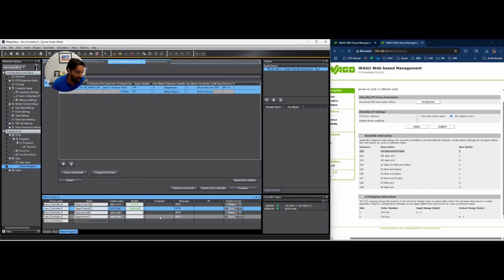Those are all on. And then if you look closely on the inputs, I can turn on some inputs, and you should see them turn on. So that's input 0, 1, 2, 3, 4, 5, and so on. So I have good communication with my PLC and my remote I/O rack, and everything is good to go.